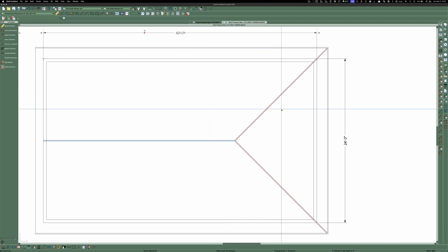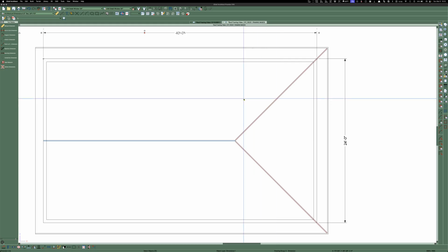And there's another thing that I had someone question. Yes, it's one rafter from the ridge out to the subfascia, but it has two components. It has a calculated rafter component, and it has an added tail component. So you do all your calculations over the things that you know, like you know that you're going to have a bird's mouth at the outside of this framing. And that's how you get that measurement. And you make a mark on your rafter at that point so that you can cut this angle. And then for the rest of this, you create a tail pattern.